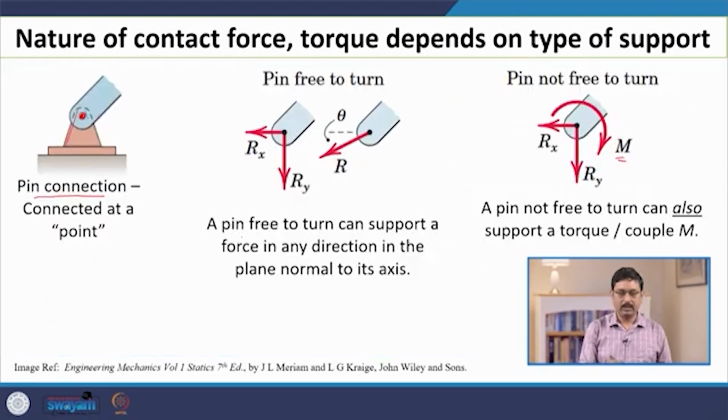Similarly, in the previous pin joint case, in general the direction of the force can be different from the axis of the beam. But if we make those assumptions, such that we ignore all other kinds of internal forces like elastic forces etc., then this perpendicular component cannot exist, and there is a simpler version where we can assume that our force will be along the beam.